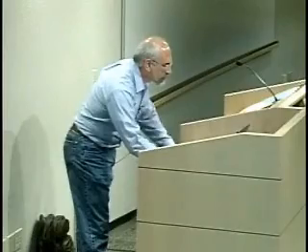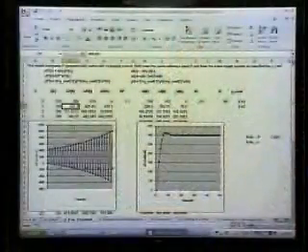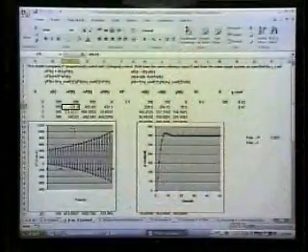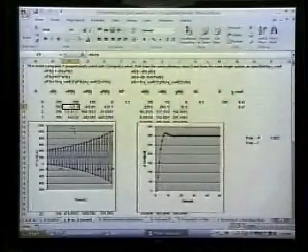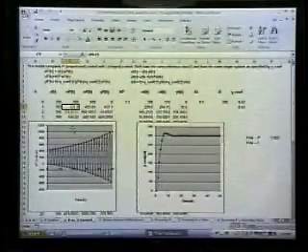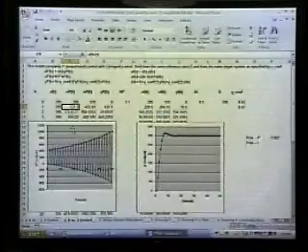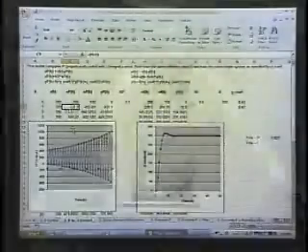Let's go across on the proportional control we've already seen before. So that's the reference input. We see here the error is just calculated within the side of the spreadsheet that does the proportional control. We're taking that B column, which is the reference input, and subtracting the measured output, the Y. And you notice, based on your question over there, time, it's all on the same line.